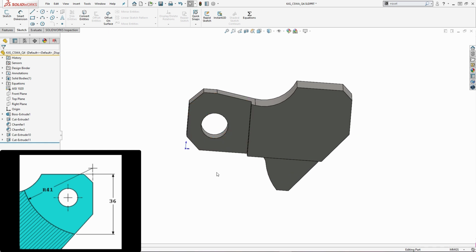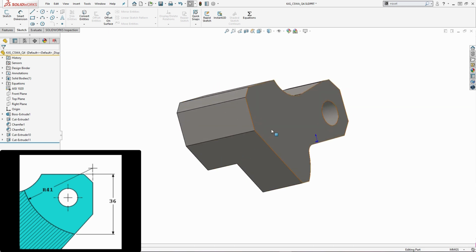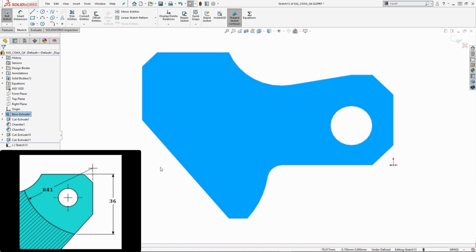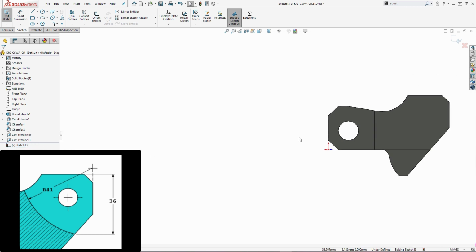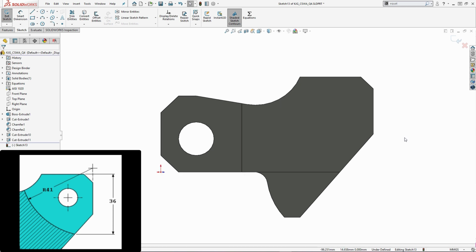The next cut that I'm going to address is going to be that radial cut. Now we know that it's not going to be symmetrical through the middle of the part. I'm going to sketch this on the back side of the part. Now, I like items to be oriented the same way that they are when I'm taking the test. It's just one less thing for me to have to remember. So I can right click on my sketch and then say normal to in the tree, and that will flip this so my orientation's correct. I'm still sketching on that back face though.